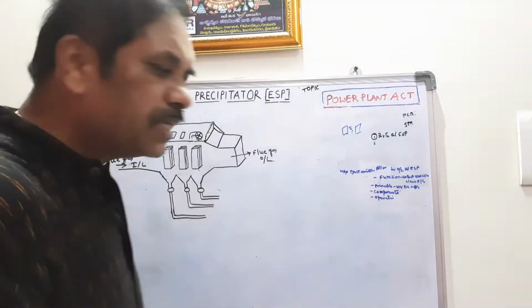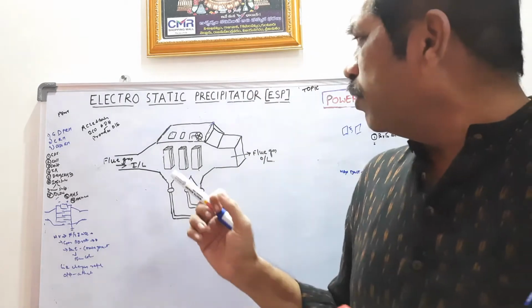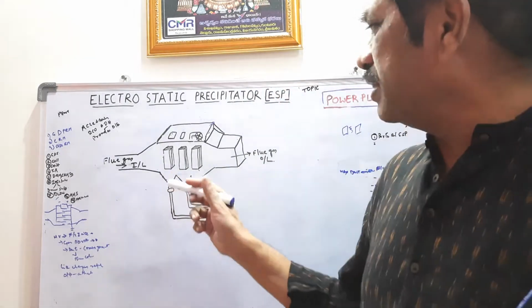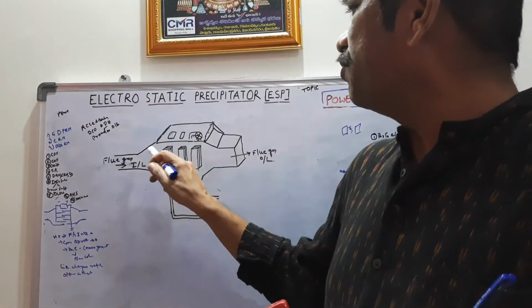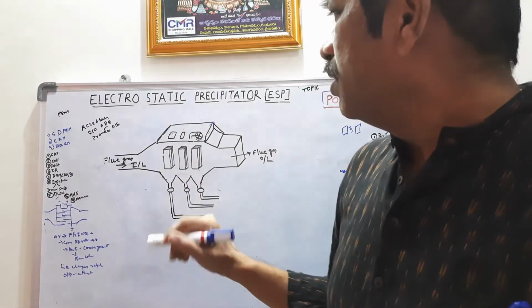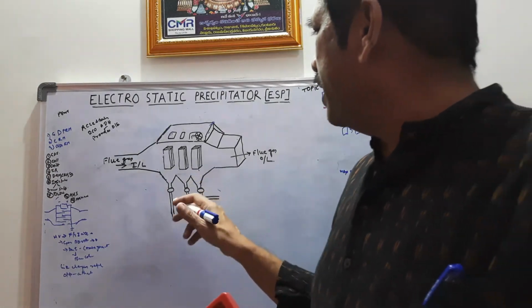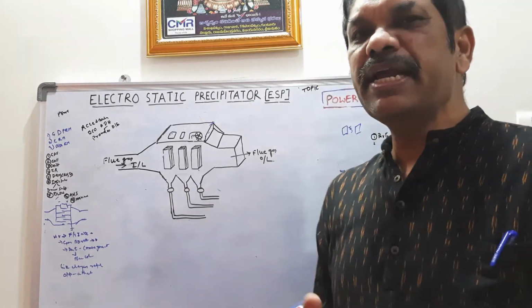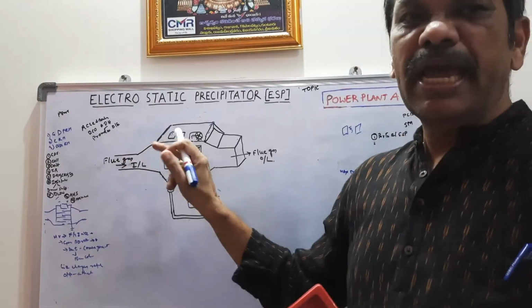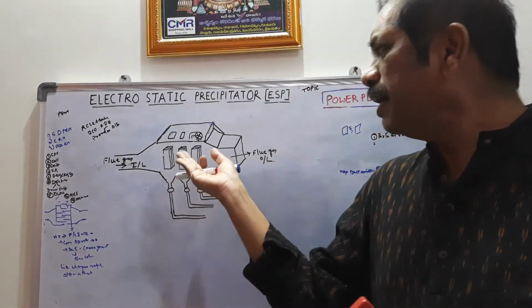In the process of steam generation from the boiler, the flue gas is also generated with high heat and temperature and a concentration of dust in the flue gas. The high heat from the flue gas is collected by accessories of the boiler such as the economizer and air preheater, and it promotes the overall efficiency of the boiler.